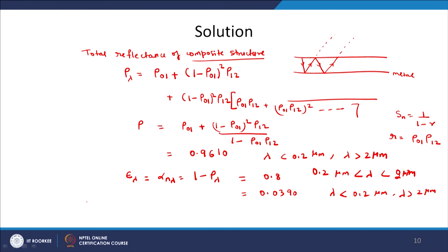So, now we find the total value, that is, epsilon will be equal to 1 over sigma T to the power 4, where T is 300 Kelvin, integrated over 0 to infinity, epsilon lambda, E b lambda at the temperature equal to 300, d lambda. And we have to substitute 0.8 here.